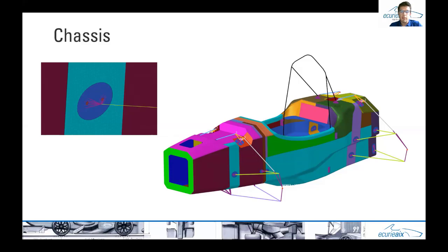And in addition, the suspension rods are modeled with tubes with our own material values, and the wheel hubs are infinitely stiff parts, and we use RBE2 elements to simulate the connections between the monocoque and the hardpoints, as you can see on the left picture. And then we are able to apply a force on the front axle on one side and fix the monocoque in the rear completely, except one side in the movement in lateral direction.